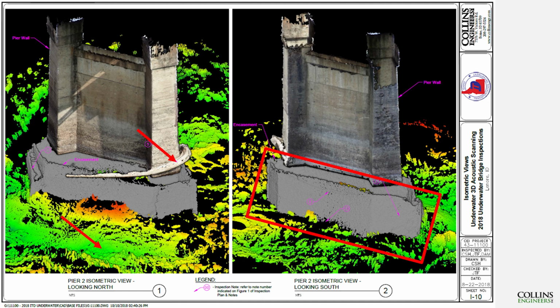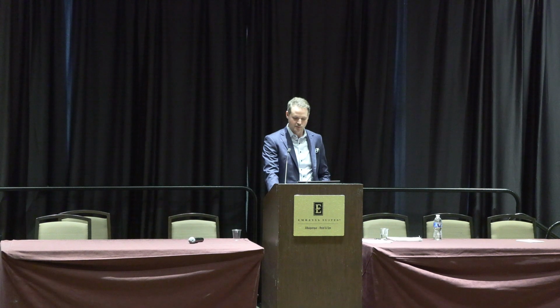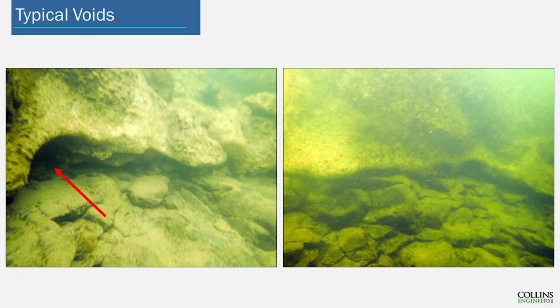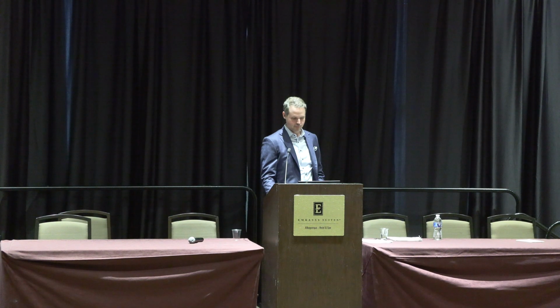In this image, you can just make out some voiding at the interface with the channel bottom, but it's kind of hard to tell with all the acoustic shadows, which is another reason why it's good to supplement a sonar inspection with diving if possible. There is that same tree that we were able to model that's wrapped around the upstream nose. Turned out pretty well. This is actually the encasements that were just below water, so that's what we were interested in for this study. So we'll move on to a little bit more about that. And that's just pointing out the channel bottom right there.